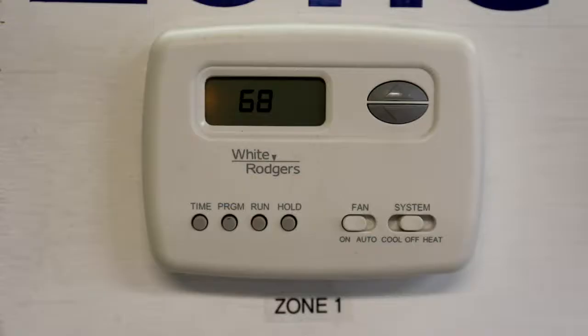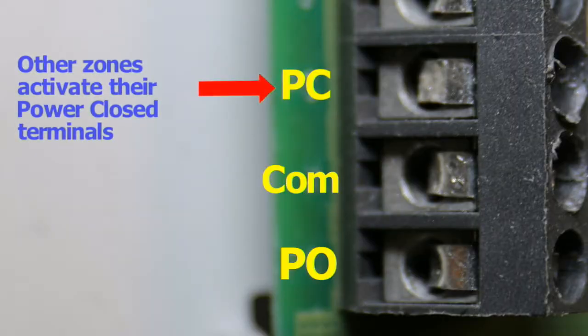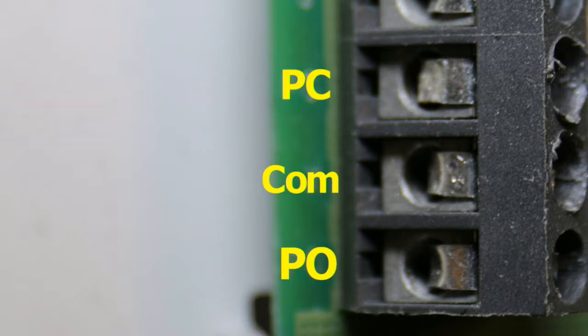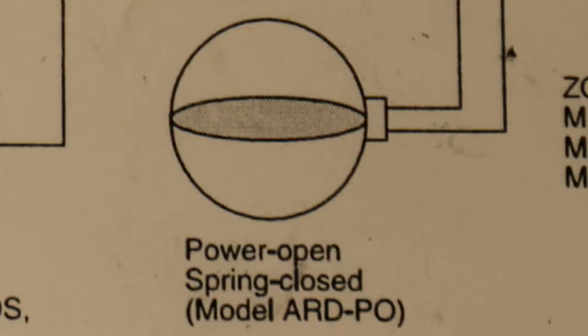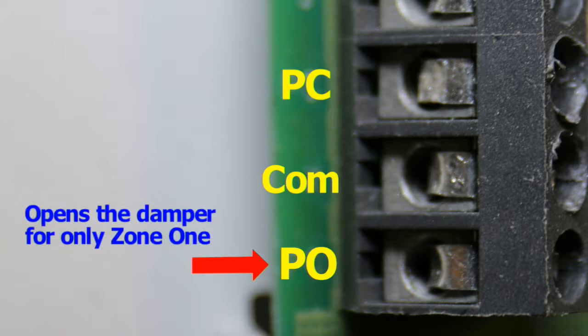For example, if there's a call for heat on Zone 1 and you're using the power closed dampers, which are normally open, the other zones activate their power closed terminals in order to close the dampers on the other zones not calling for heat. On the same call for heat in Zone 1, the power open terminal becomes energized on that zone. So if you're using power open dampers, which are normally closed, then Zone 1 will energize the power open terminals, opening the damper for Zone 1 and only Zone 1.